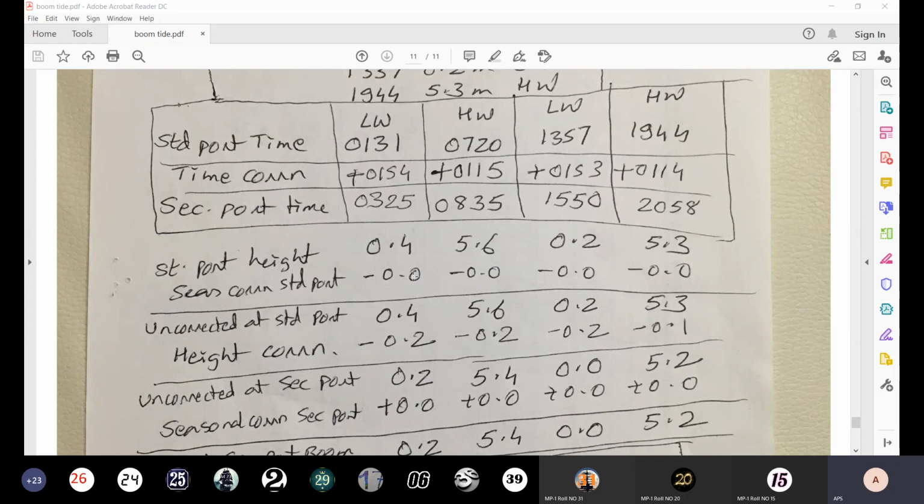So if your correction is showing as minus 0.1, then minus and minus will become plus 0.1. So what I'm saying here is you subtract the correction with the sign. Put it inside a bracket, plus or minus whatever you're getting, put it inside the bracket. Yes, I understood.